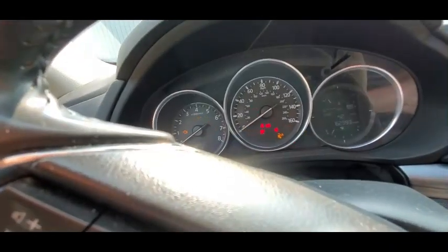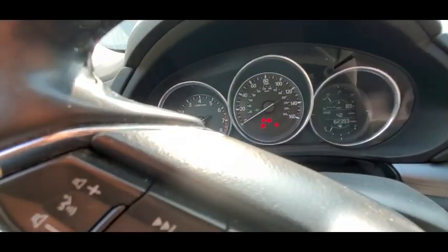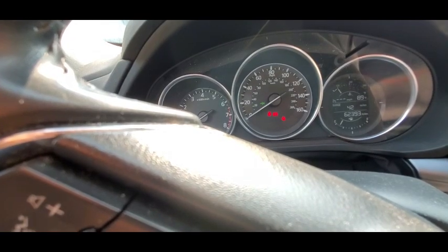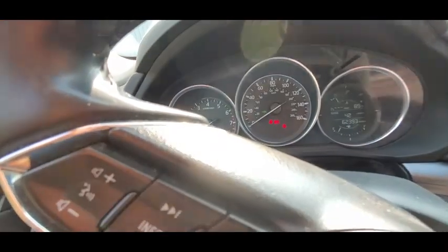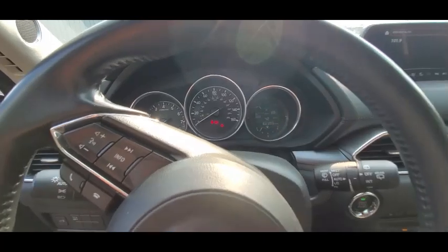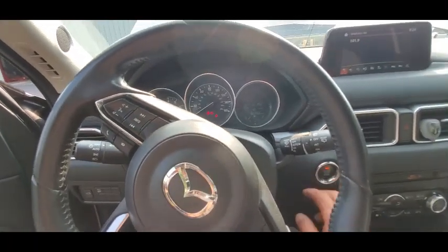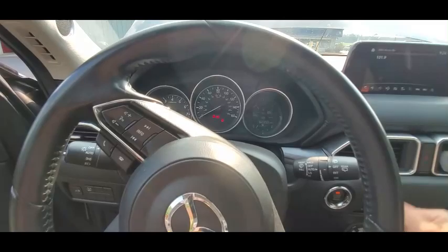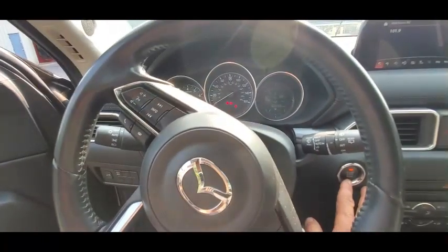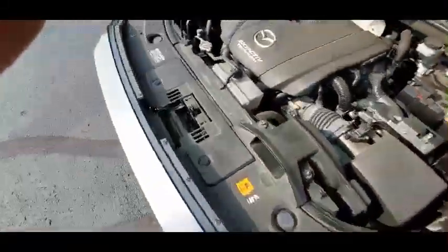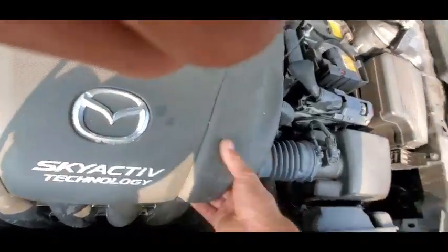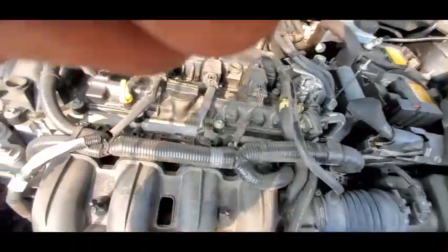Let me turn this key on. Where is our fuel level? Oh, pretty close to E. And it said on the level sensor that we were at 18%. So we're going to have to put a fuel gauge on this. There's no way around it. We've got to confirm that. I'm already suspicious of the low side pump, given the symptoms.